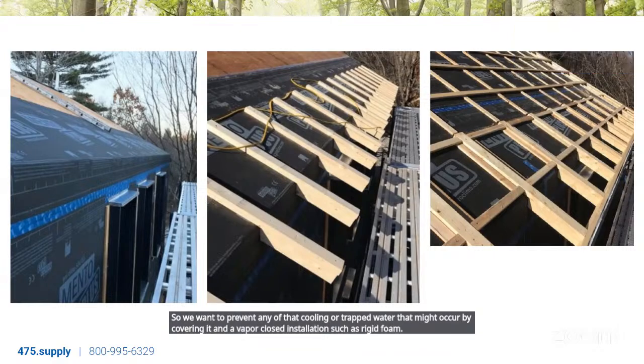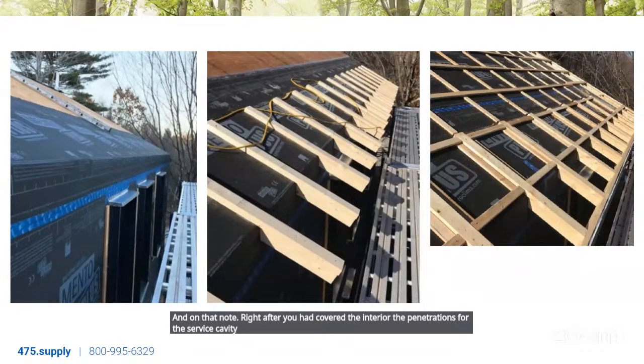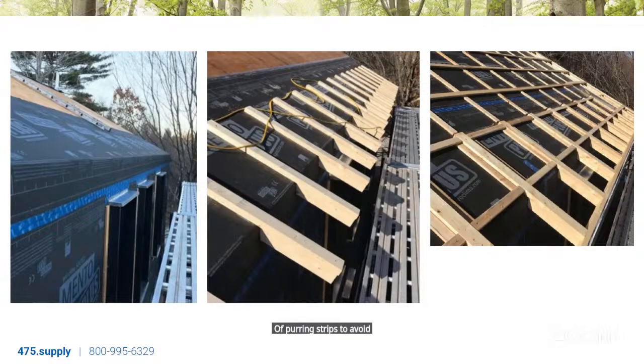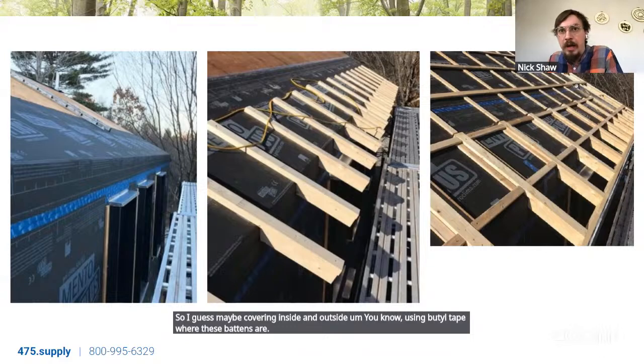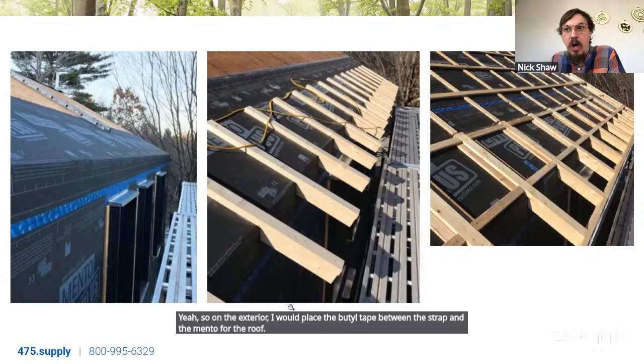And on that note, right after you had covered the interior penetrations for the service cavity on the inside, Jeffrey asked, I've seen butyl tape on the inside of furring strips to avoid a penetration. Is it unnecessary over Mento? So I guess maybe covering inside and outside, using butyl tape where these battens are. Yeah, so on the exterior, I would place the butyl tape between the strap and the Mento for the roof, but not on the walls.